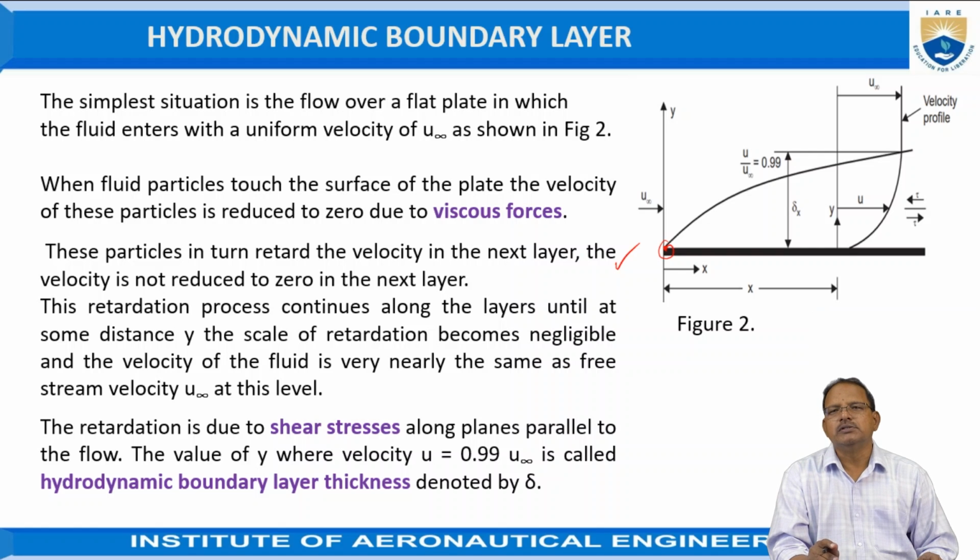So as we proceed along the length now, the viscous force between the two adjacent layers, when moving in upward directions, reduces gradually. So on moving along the length of the plate, the layer velocity gains, and after reaching a certain distance, that is the height of delta, it gains a maximum velocity, that is the velocity of the fluid at the initial stage.